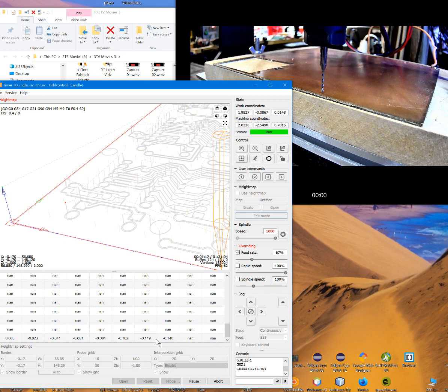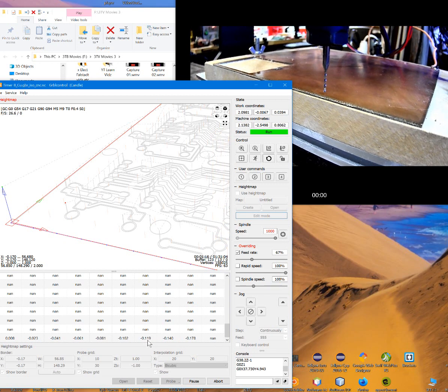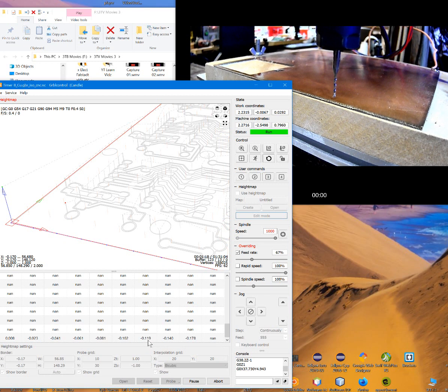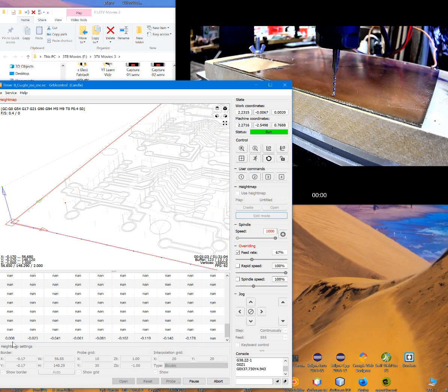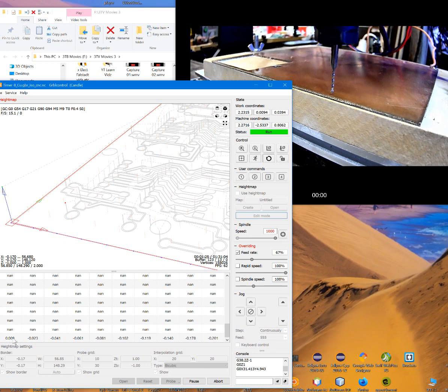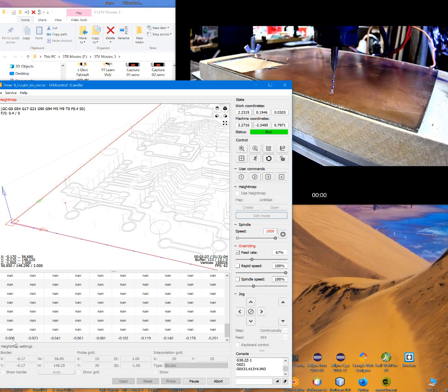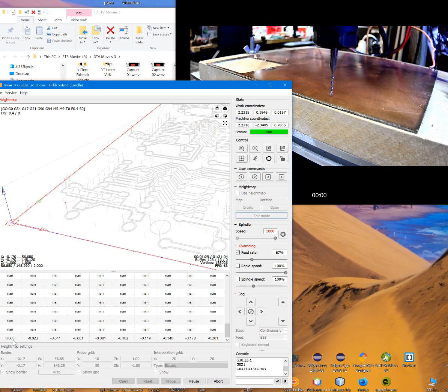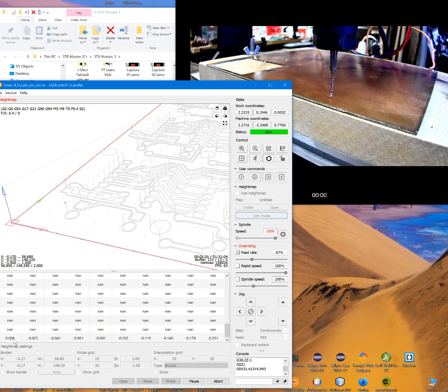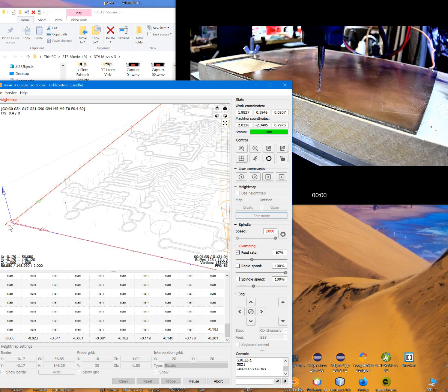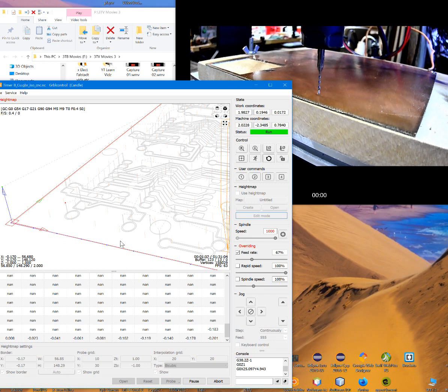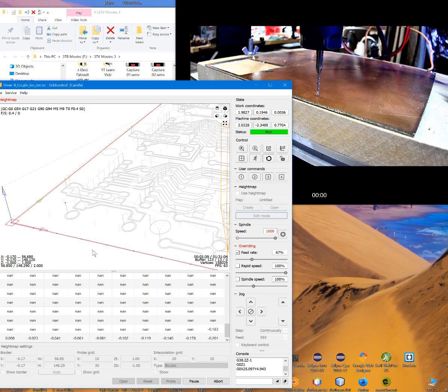You can see it's generating height data. Now remember, these are all in millimeters, and this negative sign is telling you it's minus 0.119 millimeters below where the origin is. I wonder why that's at 8. Yeah, that's strange. Normally that's at 0. I don't know why that would do that. Oh, it's probably because it's in a different location. Because our home is here, but our grid, I think, starts over here. So that's why it did that.